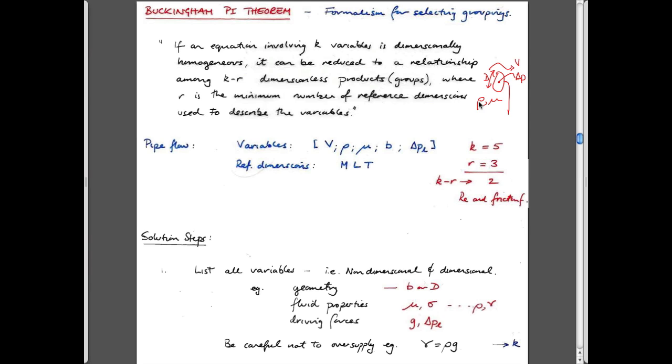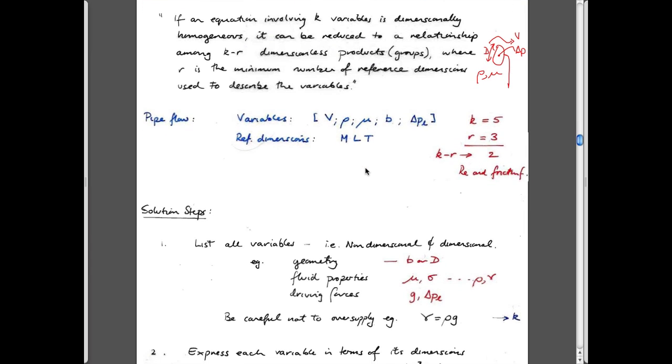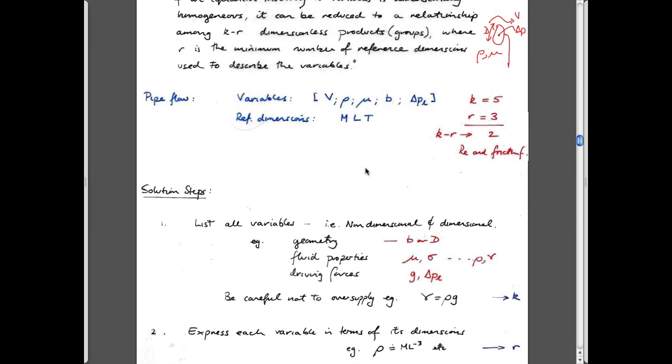then there's a formal way to be able to take those variables and do a couple of different things. One is you can figure out how many non-dimensional groups will describe your system, if you know these variables, and if you know whether mass, length, and time is represented, just by taking the 5 of these, subtracting away the 3 different dimensions that are represented, and then dividing them up in terms of repeating variables and dependent variables.